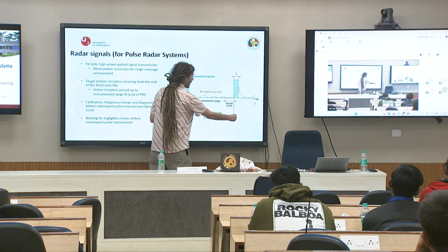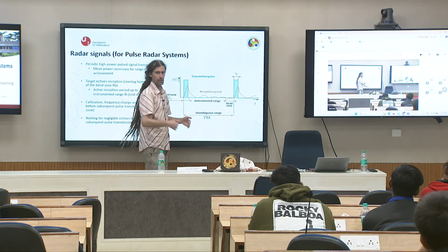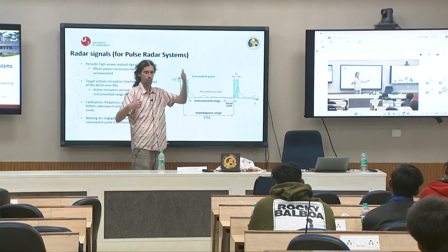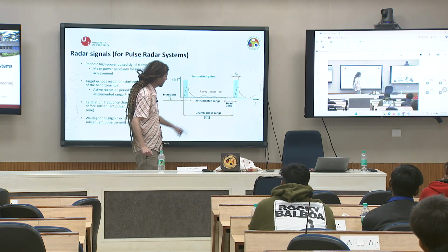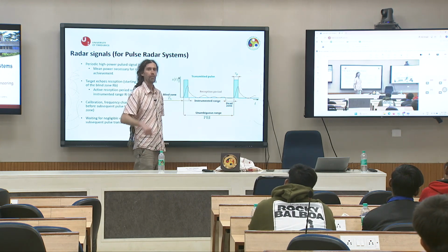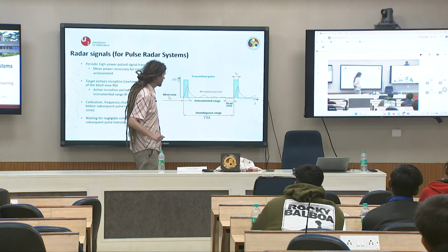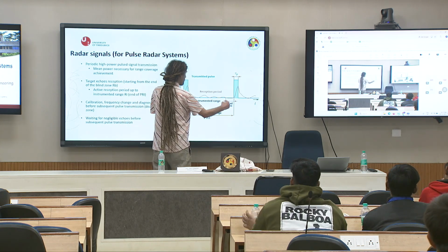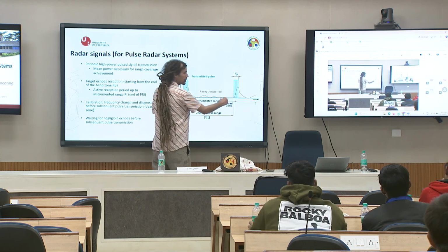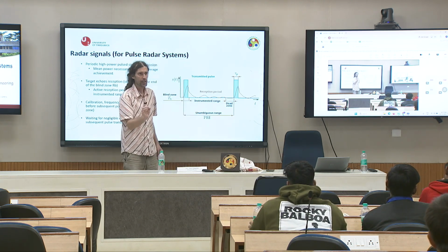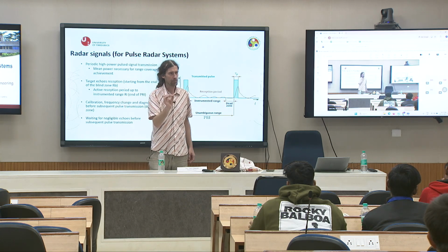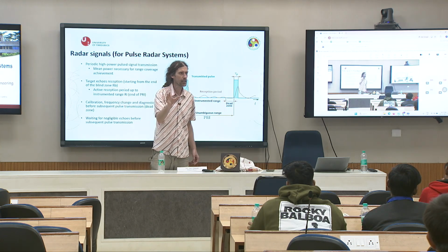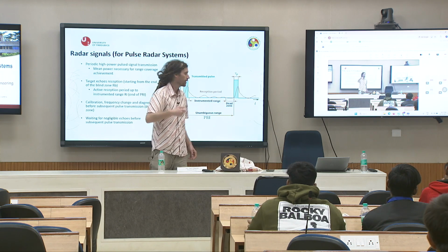This is PRI. It is the difference between two pulses. It is clear. The inverse value is PRF, pulse repetition frequency. There is the instrumented range, and what does it mean? It means where my radar is listening and receiving signal.